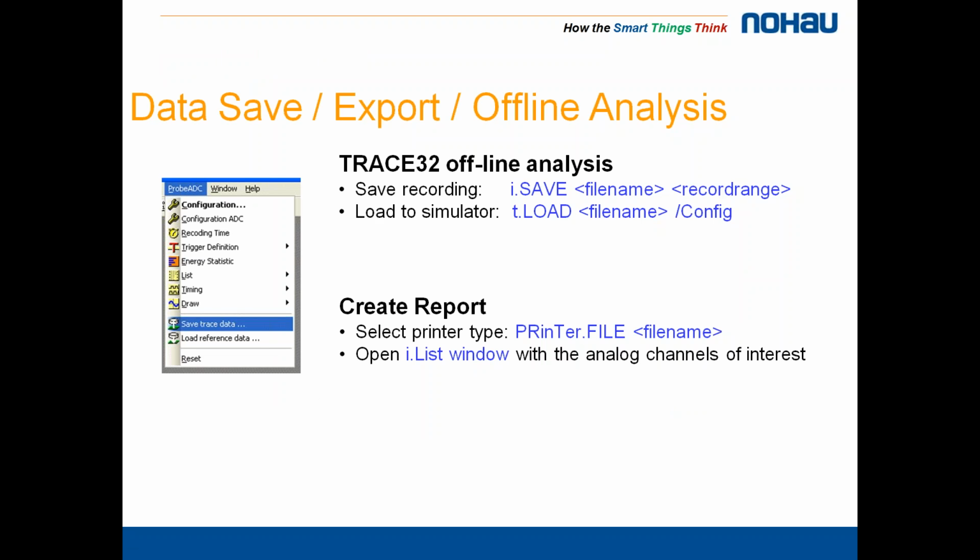You are also able to export and save the data for later analysis or create a report. So you can store your trace buffer with the program flow, and then you can store your, let's call it, energy buffer, where you have your current and voltage measurement.